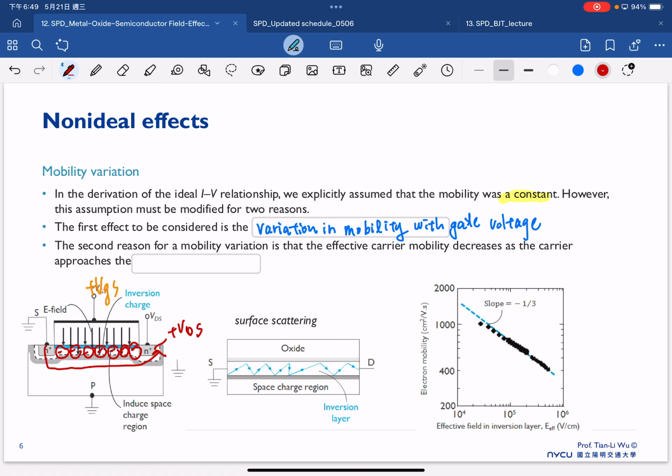But what we didn't mention is that these electrons are also suffering the gate bias here. That means these electrons would also like to flow from the top toward the gate, because our gate bias is positive, right? The idea is that electrons flow from source to drain because they are attracted by the positive drain.